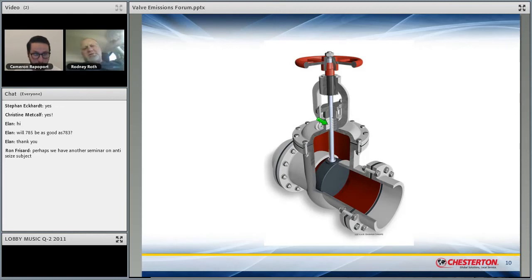Yeah, and this picture actually shows it as one piece. Yep. That's not standard. There are people that make one-piece glands, but the standard is those two components work independently of each other, and they have to be self-aligning. So the gland has an angled top to it, and the gland flange has a concave in it, so that when they come down, they cinch on each other effectively.